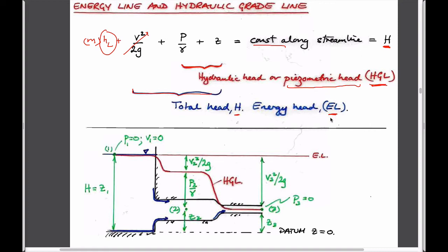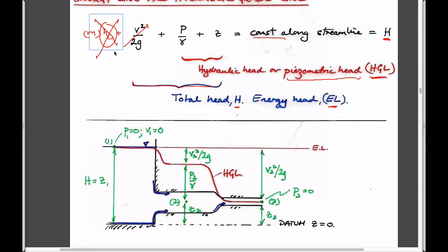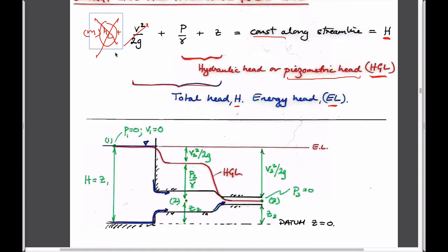The significance of those is that in the absence of any viscous losses, due to fluid flowing in little capillary tubes in the pores of porous rock and losing energy by friction, generating small amounts of heat, the magnitude of this energy head should always remain constant across the system.